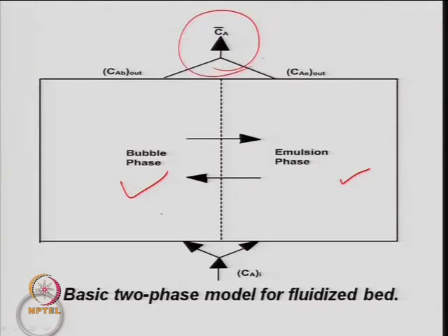So, we have modeled it like this, but this is your black box where you need to evaluate the parameters and match it with this, your input and this, your output, right, and that will decide your conversion, whatever CA bar by CAI, or one can calculate the X or mean conversion based on that. But the actual conditions inside the bed will depend on the gas velocity, superficial gas velocity, density of the solid and size distribution of the solid.